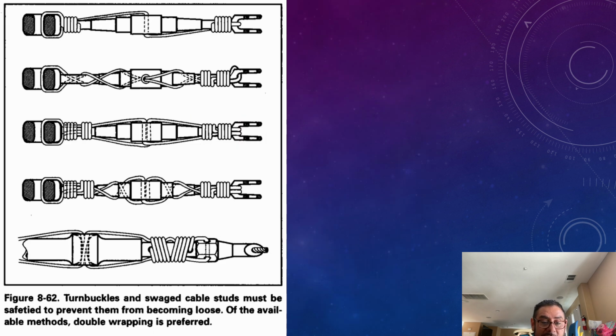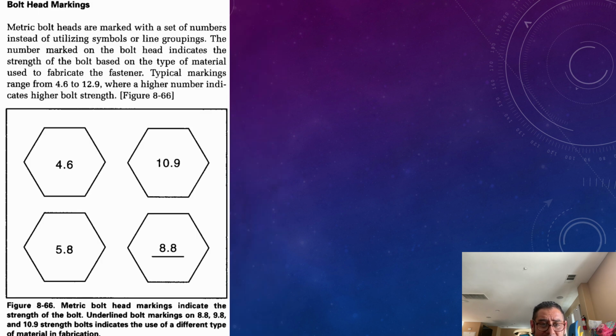All right, turnbuckles and swage cable studs must be safetied to prevent them from becoming loose. You should pause this, take notes. So a lot of you already did this project, but it's something that you need to get familiar with.